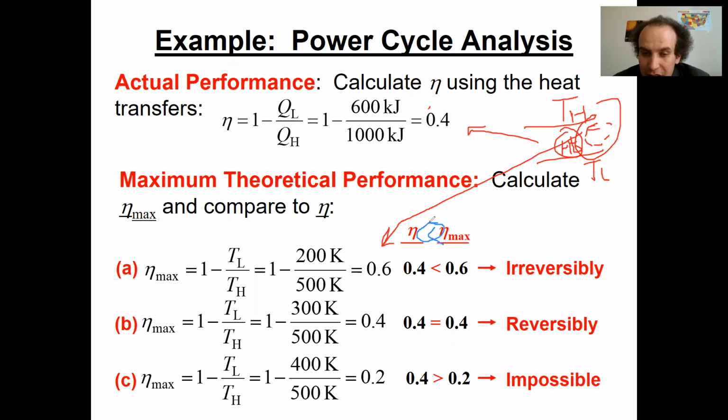The same story oppositely. If your maximal efficiency is 60%, but your calculations give you 60.001, again, it's impossible. And if your calculations give 90%, again, it's impossible. It does not matter how far, just larger or smaller. Do you understand this? That's what's going on. And from here, it gives you one more hint when you solve the problem. So you have equations like this. If you know fewer terms, but it's stated it's a Carnot cycle, then you should be able to compare and combine it. Does it make sense for you? Do you understand? That's how we solve this problem.